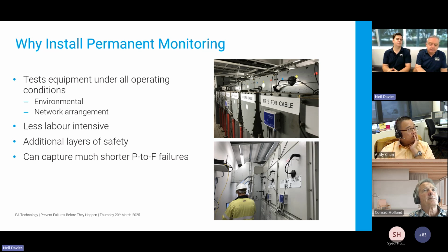Over the past many years where we've been testing, we've all come across the sort of issues where you're going in to test a switchboard. A particular circuit breaker is open for a day because maybe a pump is not operational at that time, and then when the circuit breaker closes, the pump comes in and there's a discharge on the portion after the switchgear.